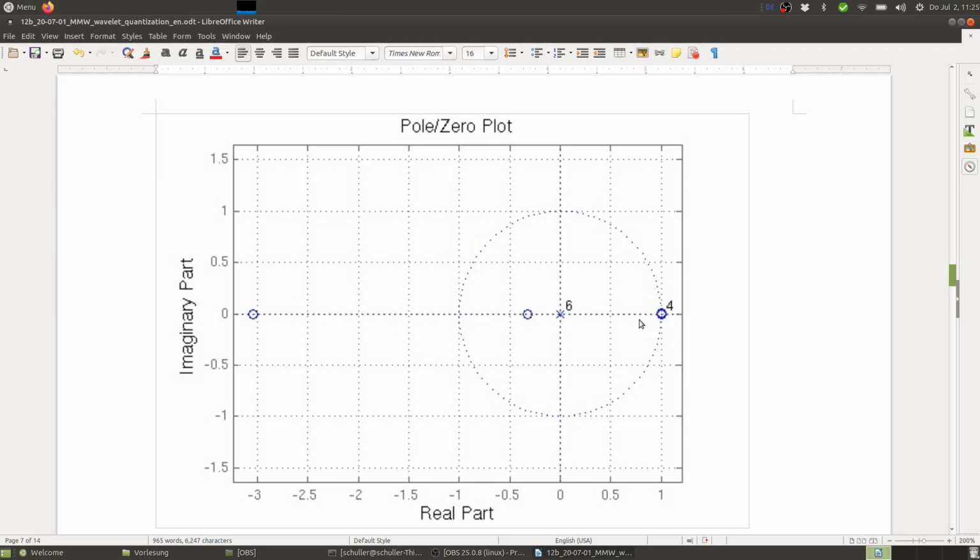And the frequency response can be estimated or guessed from looking at this z-domain plot by seeing this unit circle around the origin. Right? This unit circle corresponds to z equals e to the j omega. And if we substitute z by e to the j omega, then we obtain the discrete-time Fourier transform, which we use for obtaining our frequency response. Right?